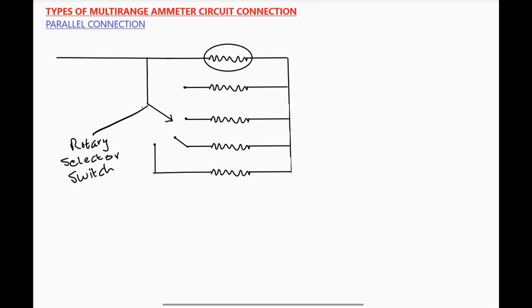So every meter has a full-scale deflection current, IFSD. This is my ammeter here. It has a full-scale deflection current IFSD. This is the maximum current which the meter can measure. Expanding the current capacity that it can measure requires the addition of a resistor to the meter coil.